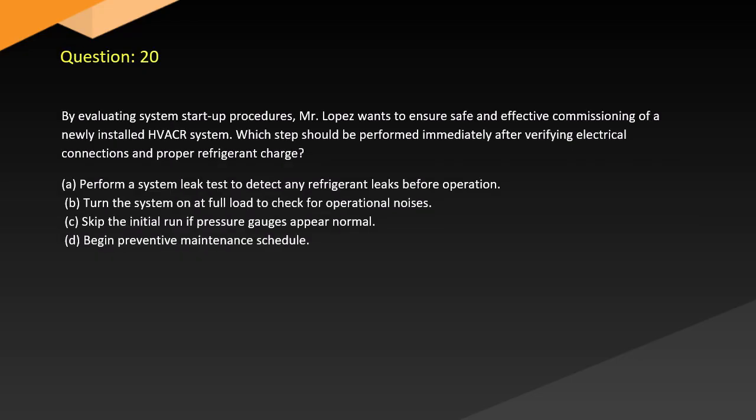Question 20. By evaluating system startup procedures, Mr. Lopez wants to ensure safe and effective commissioning of a newly installed HVACR system. Which step should be performed immediately after verifying electrical connections and proper refrigerant charge? A. Perform a system leak test to detect any refrigerant leaks before operation.